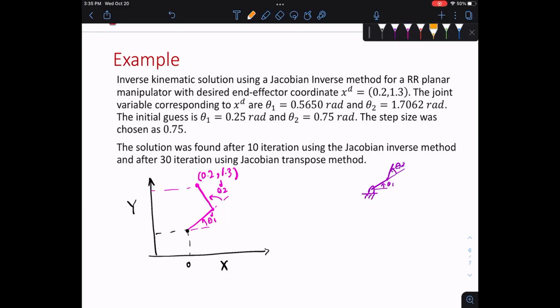You see that this will immediately tell you that, hey, I have another checkpoint. After I figured out theta 1, there will be a point for theta 2. It could always be lefty and righty also, correct? So you have two options basically when you find this. But now when you're using an algorithm, you're trying to figure out the convergence, you want to just go one way, right? Find one solution.